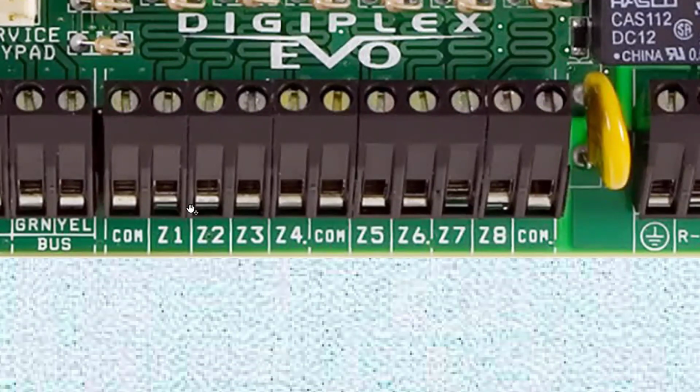We have the terminal strip for the zones. We have to be able to connect some of the devices. For the most part, it works like this. You got common, and you got common, and you got common here. Every once in a while, you're going to have the common. These are the same terminals. This one here electrically, actually physically, is connected to that one. It's just those common points are distributed for easy access if you go further along, right?